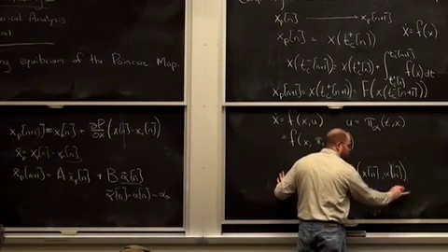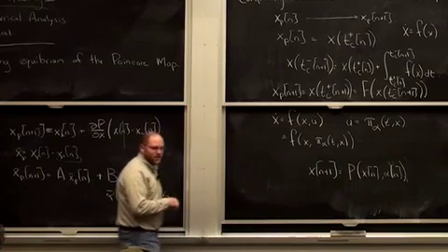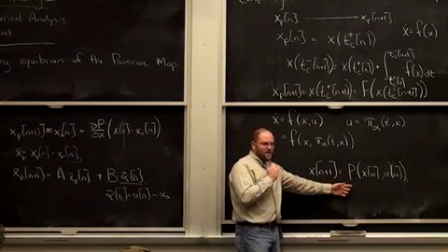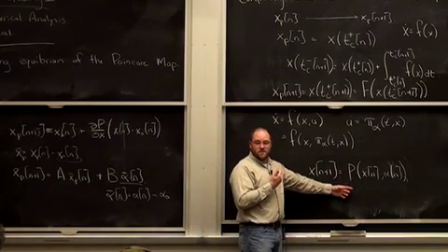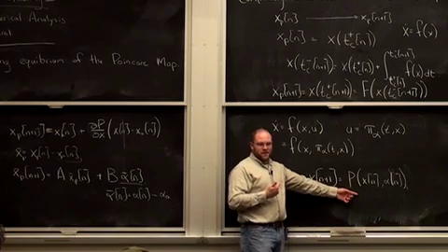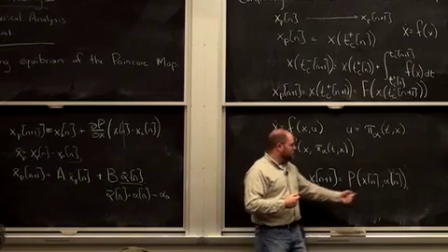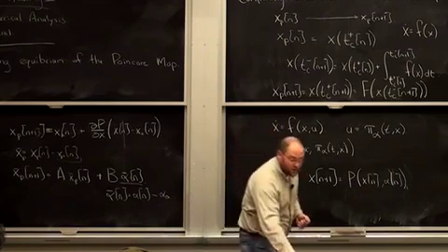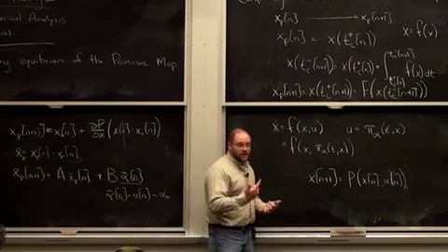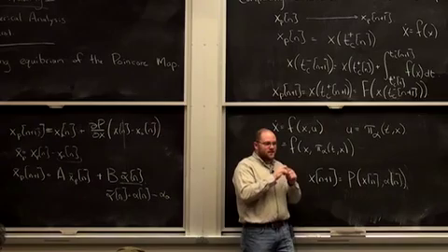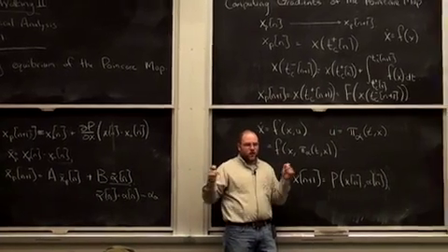And it's just about the right size that you can try discretizing and doing value iteration. So Katie had some nice work showing that on the compass gait we can really get a pretty good sense of the nonlinear optimal solution by just popping this discrete time control problem into value iteration, doing some work, and computing back an optimal feedback policy which tells you where you should step every time in order to stabilize your gait. One better, if you add one more dimension to your compass gait robot, you can actually think about where it is on terrain and make it walk over rough terrain.